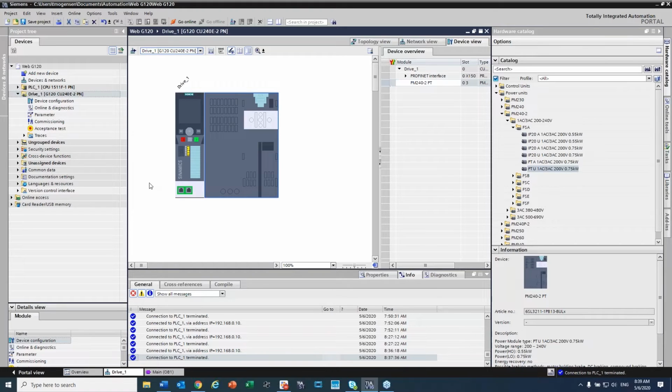Okay, now that we have the drive in our system, we have to think about a few things on how we're going to get the drive to communicate and work with the PLC. Siemens has set up a bunch of different canned telegrams that will give enough information to control a drive and make a drive run. Some with encoders, some without encoders, some with just a control word, some with a control word and extra data. For this example, what you signed up for was an example using Telegram 352, which is a standard from Siemens that not only allows you to control the drive and run the drive, but it gives you some information back like amps and current and torque and faults, pretty much everything you'd want out of a general purpose drive. So everything we do here, we're going to go for Telegram 352.